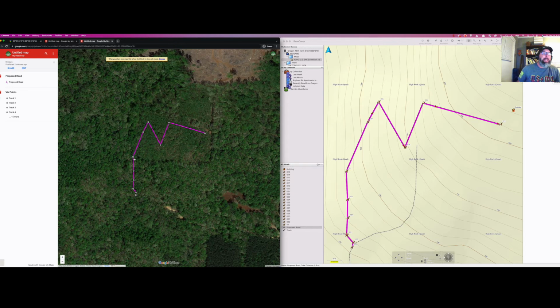Just skirt up the backside of this guy's property, and then start uphill. Switch back to come here, and switch back to here, and then turn toward the building, which is right here. And this will be a parking pad in this little area. At no point would it have exceeded 10% slope. And here it was actually like 5 or something like that. Not much at all, but you've got between 9 and 10 going up the rest of the way.